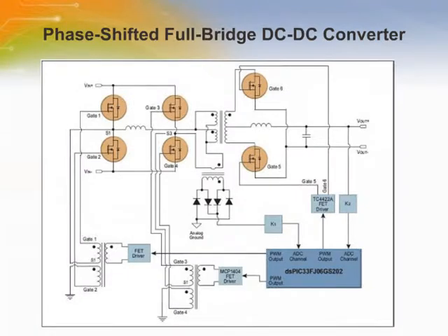The dsPIC33FJ DSC family enables power-efficient and highly integrated DC-to-DC converters that dynamically control different power stages. High-speed analog-to-digital converters, pulse width modulators, and comparators work together without using much CPU bandwidth. Faster digital control loops and compensators can be executed using a high-performance DSP engine. Advanced features such as dynamic load response, protection, sequencing, remote control, and communications can also be implemented.